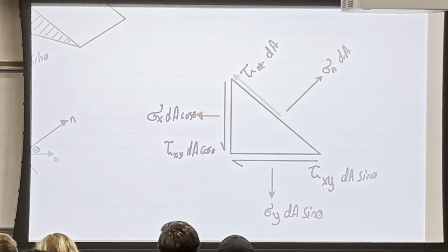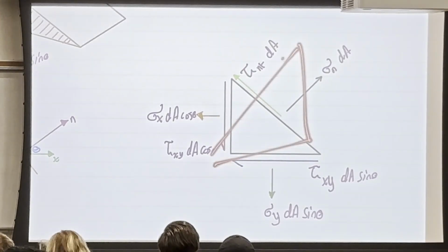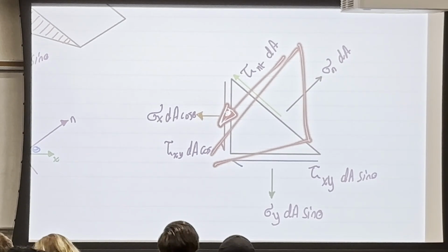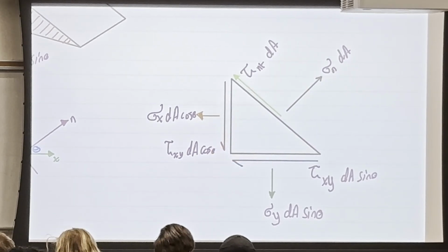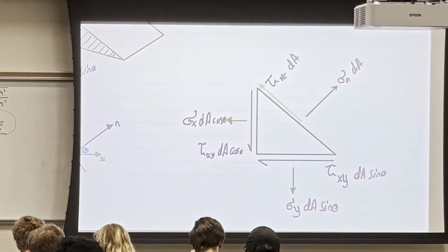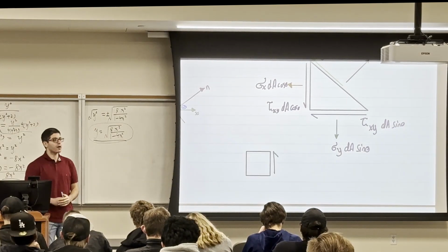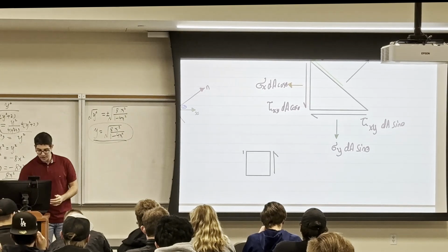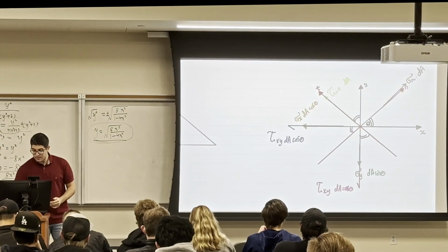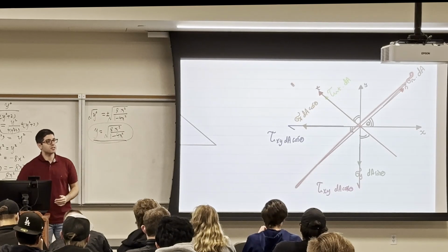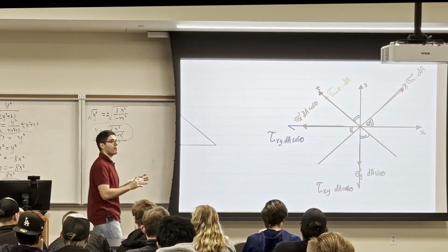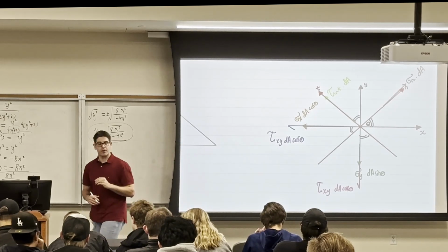But if you have tau equal to negative, that means the plane that you are working with no longer has this tau looking that way. That means, for example, you have this plane, and the tau is now going to look that way, which means your assumption at the beginning that the tau looks up is incorrect and you should invert it, which also aligns with the sign convention for the shear. I have one side going up, and where is the other side for the positive sign? It's going down. But this equation doesn't see it. This equation is summing from one side and summing from the other side. This equation doesn't know about the sign convention for the shear. Is that clear to everyone?